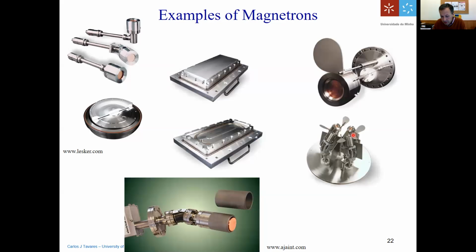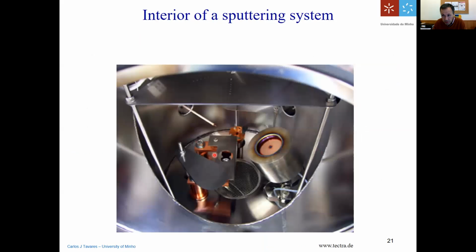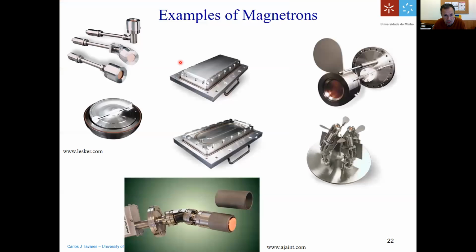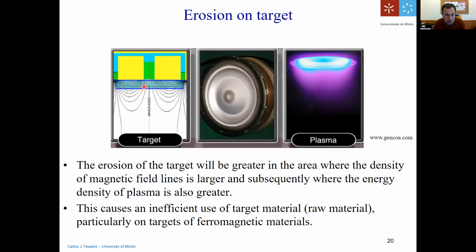But for the selenium part, you have to do thermal evaporation. And here, these are targets which are used in the industry. You can see this person here operating a magnetron, which is extremely big. It's a rectangular target placed on top of a magnetron. Normally, it's fixed to the bottom part of the magnetron so that the water can flow beneath the target and cool the magnets, okay?